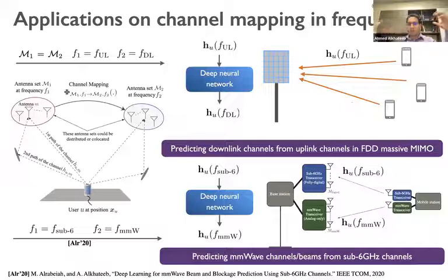So if you now look at the CSI compression, then this codebook could actually be a very simple codebook. It may not need to compress the full channel. It may have just a very low dimension channel. So it may help in reducing both the training overhead and the feedback overhead. So it's kind of a hybrid solution where you rely on machine learning to reduce the dimensionality of the problem, and then you rely on classical over-the-air training to obtain the final channel information.